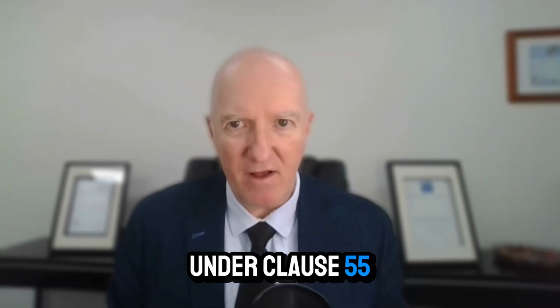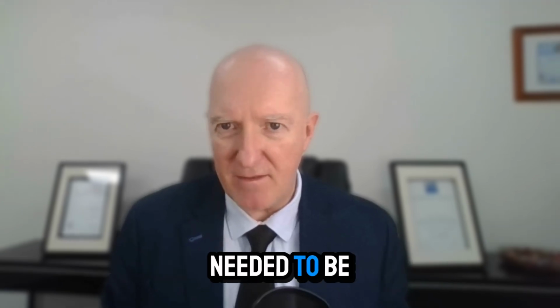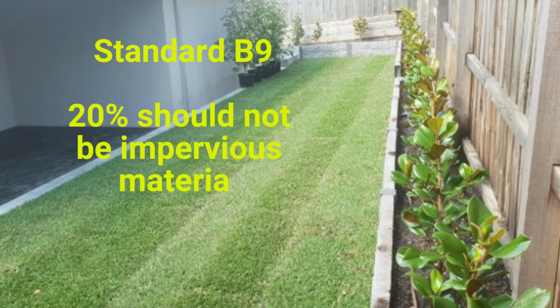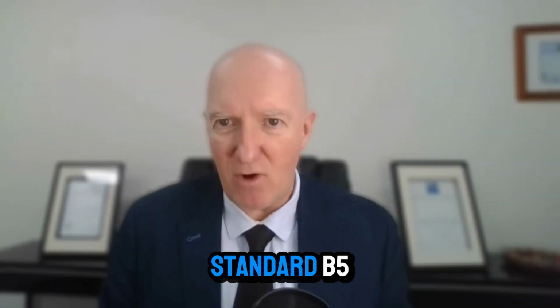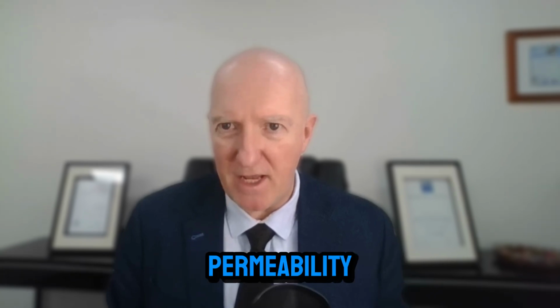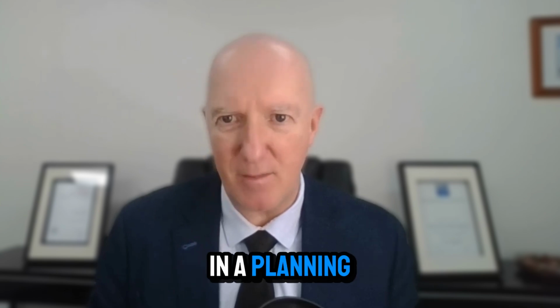Under Clause 55, permeability was previously Standard B9. The requirement that needed to be met was that 20% of the site should not be covered by impervious material. The way to meet this standard was simply to show on a plan that 20% of the site was lawn. Standard B51 in Clause 55 now requires the consideration of both permeability and stormwater management and requires additional information to be included in a planning application.